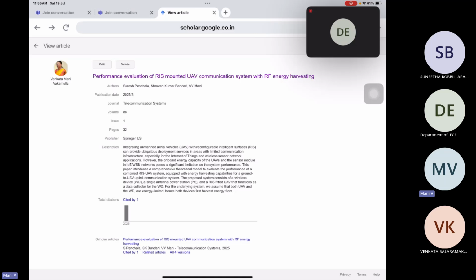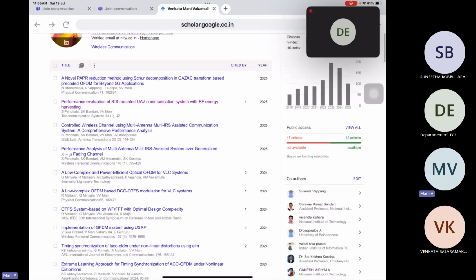There is another technology called orthogonal time frequency space system, OTFS. That is one of the technologies where we divide the system into a two-dimensional plane. We take the three-dimensional into a two-dimensional plane. Delay is separate and Doppler is separate. We combine both of them into one domain so that we can eliminate this Doppler shift. Okay, that is one of the areas we are working on.